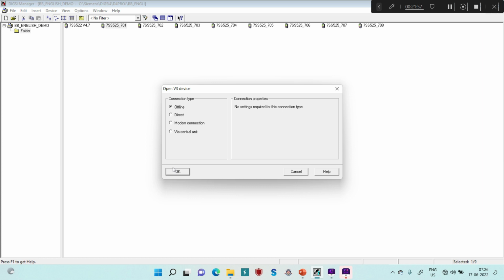In some new schemes, in some new projects of Siemens, they are providing additional communication cards or additional communication circuits for communicating with your bay units through the rear port or over the Ethernet. But in older schemes or in most of the substations, you must communicate with this bay unit only through the front port. So if you are sure this is the latest project, then it is well and good. Otherwise, first of all, communicate with your relays through the front port, all the bay units, save the settings, save the configuration in your laptop, and then start working.